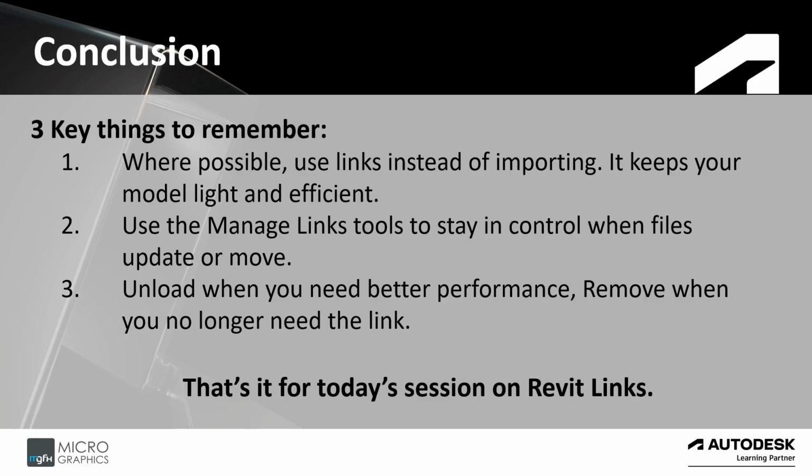So three key things to remember. Where possible, use links instead of importing. It keeps your model light and efficient. Importing makes it a part of the project. Linking makes it an external reference, keeping your Revit model file smaller.